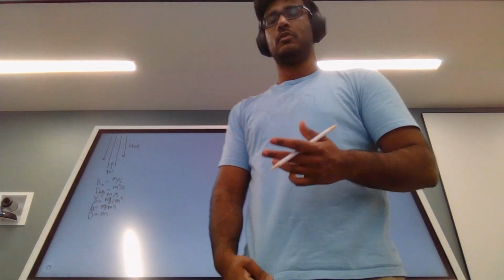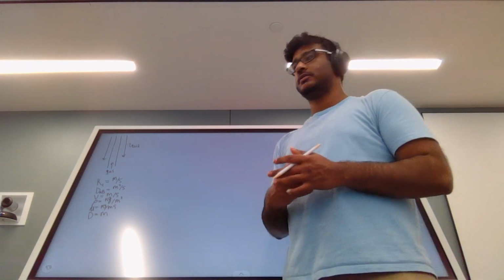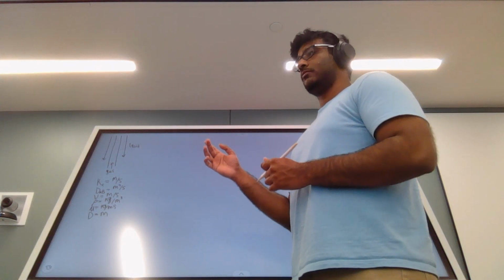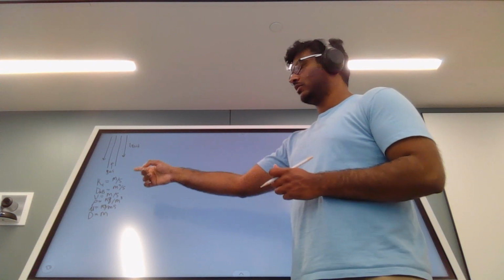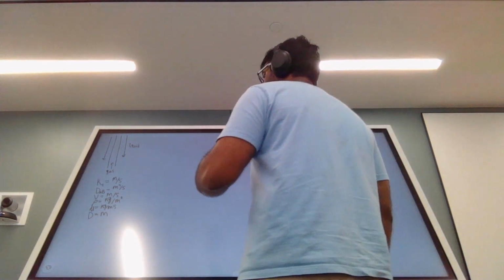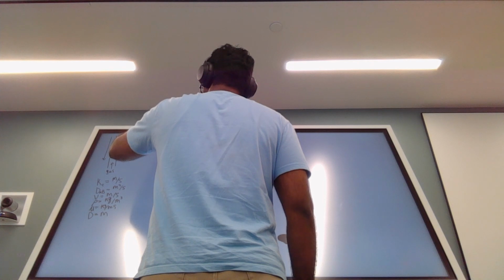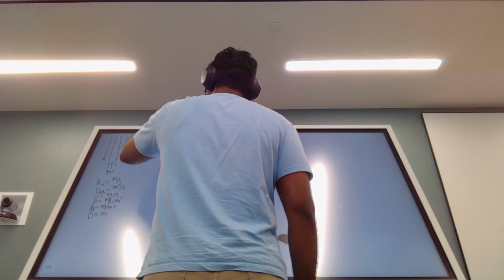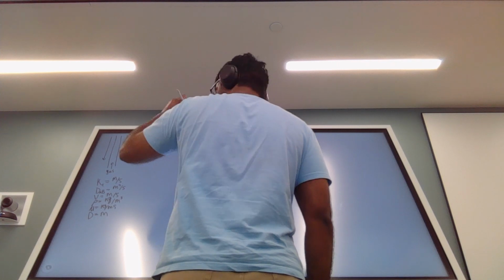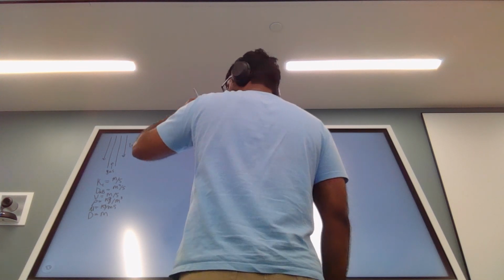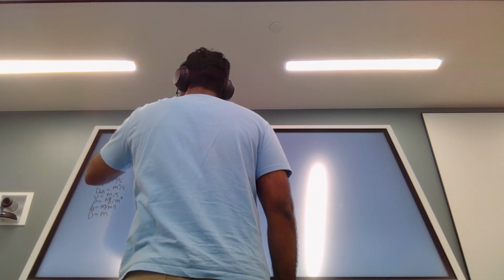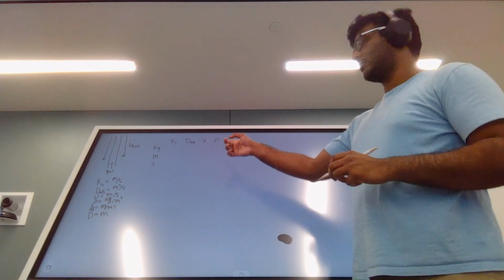So now, since we have all of our units for each variable in place, what we're going to do is create something called a matrix. Our row up top is going to be our variables, and then on the side we're going to have kilograms, meters, and seconds. So let's go ahead and write that. Kc, DAB, V, density, viscosity, and diameter. And then kilograms, meters, and seconds.